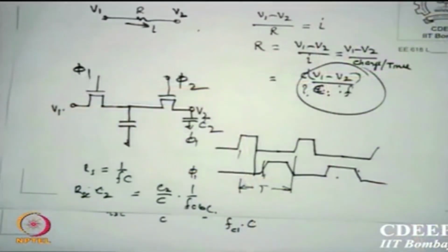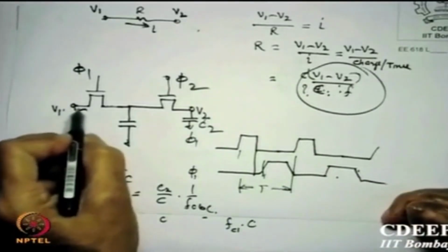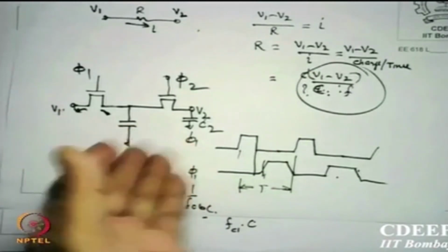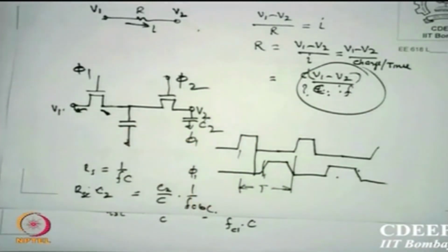When you make phi 0, you expect this charge to collapse. Where can it collapse? Either at the source end or at the drain end. The charge has to be withdrawn, but there is a capacitor sitting here, and it charges that. So the next value starts with an offset.